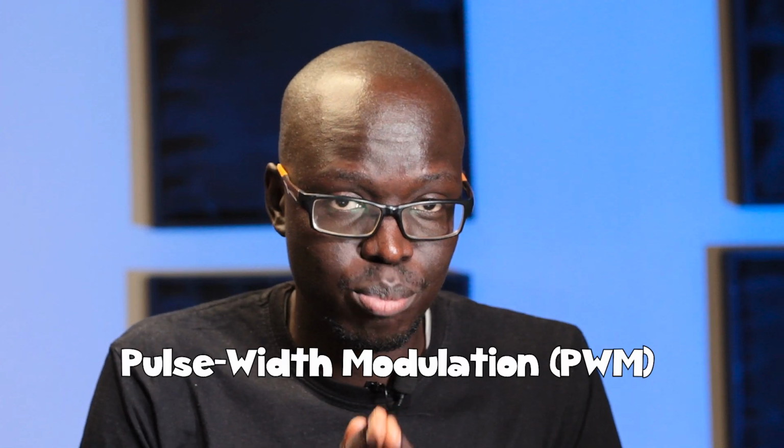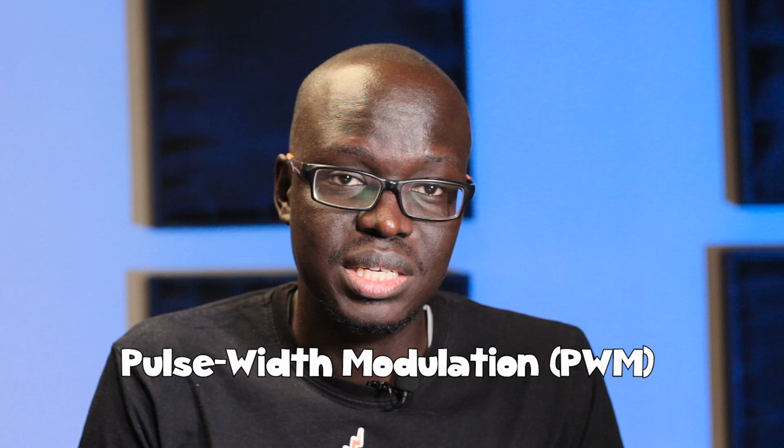But what if we wanted it to have this gradual on and then keeps getting brighter and brighter and then gets to maximum brightness and then goes off all the way down, right? So to do that, we need to simulate an analog signal using digital signals. All right, so bear with me here. So for this, we're going to use something called pulse width modulation. Pulse width modulation, in short, is called PWM. It's a way of faking analog signals using digital information.